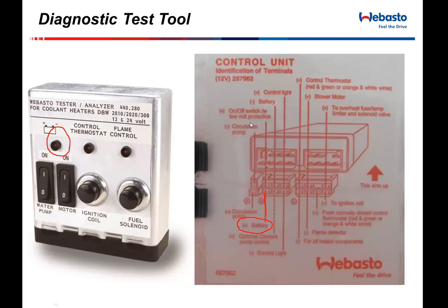The switch or the timer is ultimately coming through onto B1. If everything is closed on the top of the heater, the regulating thermostat, the overheat, and the overheat fuse are all closed, and I jump B4 to B1, the heater has to take off. It has to operate. If it doesn't, then this control unit is bad and needs to be replaced.